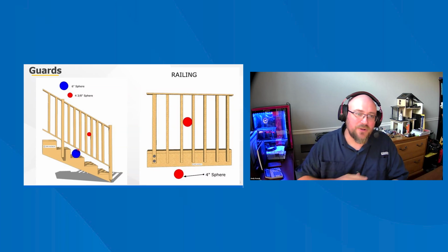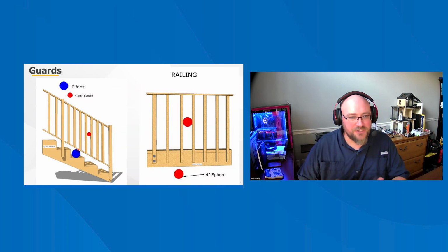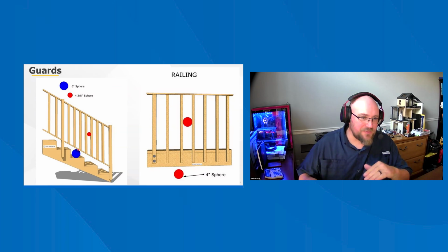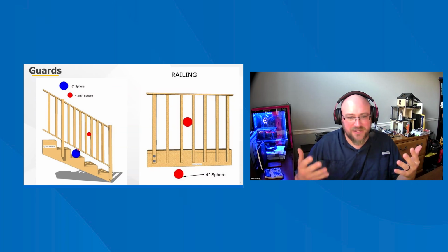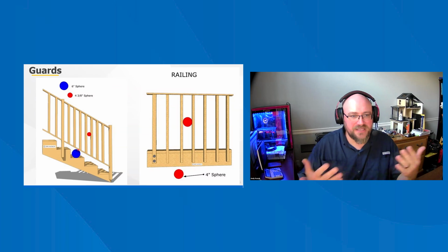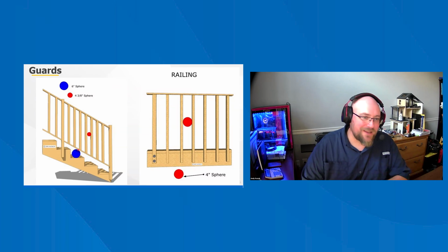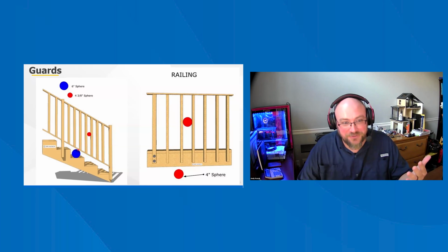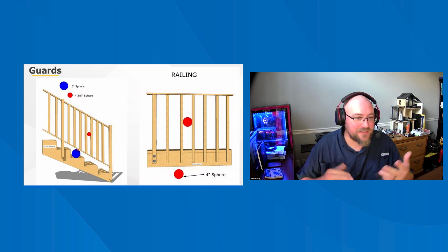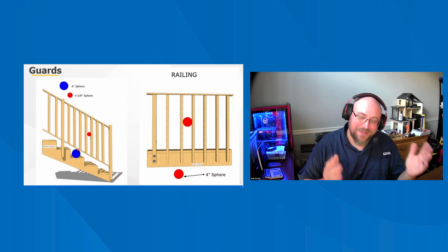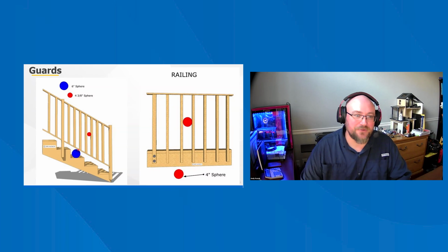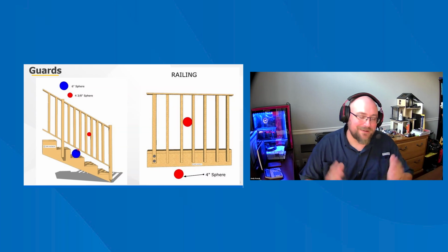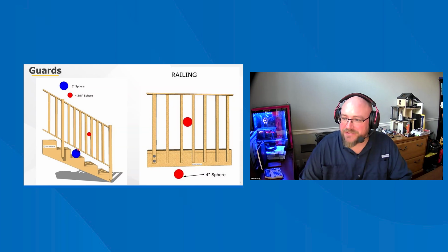So even though it's pretty standard across the board now on new construction that you've got those cable systems or chicken wire that's used as railings or whatever, I always call it out. My first question to the client is, hey, are you going to have any children in this house at all? Family, friends, or whatever? If there is, I recommend you upgrade this to vertical spindles and take out the horizontal portions. That's just on me, but that's the reason for it.